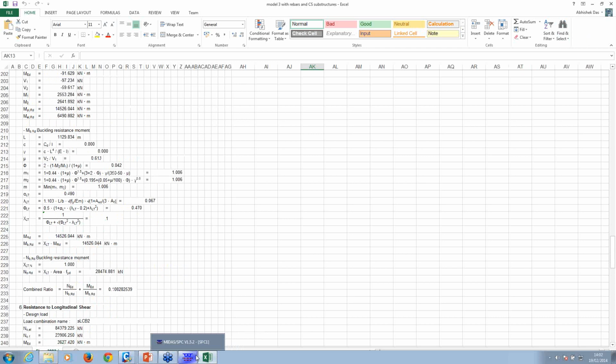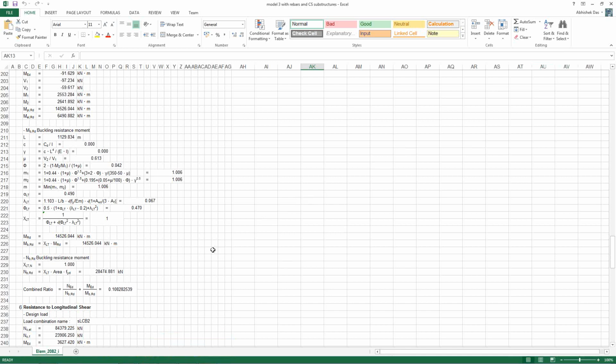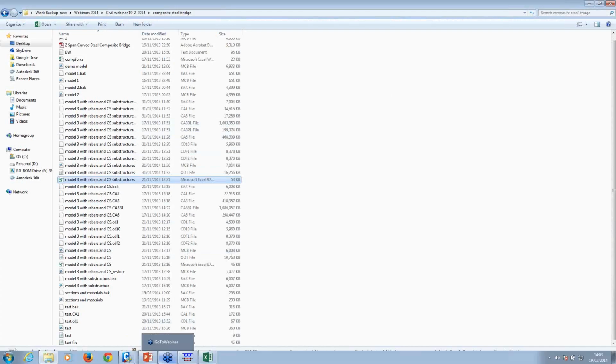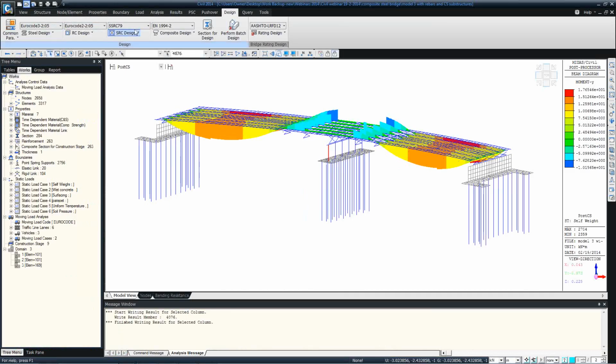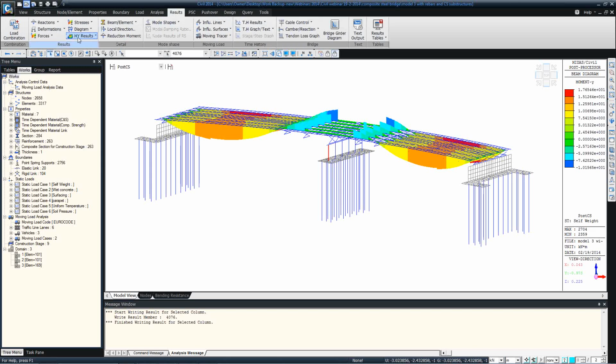Okay, there is another question. Can you show the beam and plate results at the same time? Because these are two different types of elements, so beam forces and plate forces, they are displayed separately. Beam forces and truss forces can be displayed at the same time because they are both line elements. But for the shell elements, you have to see it through the plate force diagrams. So that's where you see the plate forces, and you can also sum up the plate forces to get the equivalent beam force.